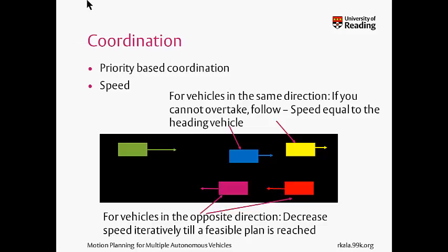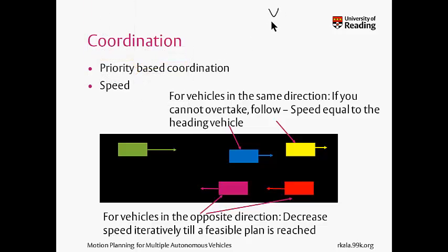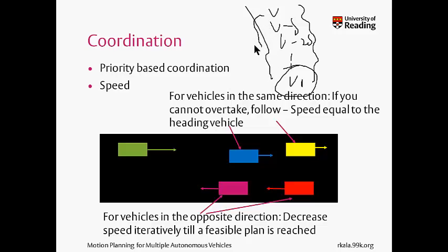The second thing that I said there was that speed is iteratively reduced from v to v minus delta to v minus 2 delta. Now this is a very bad procedure. I'm calling the complete RRT so many times in order to get the highest possible navigable speed here. I cannot waste this much time by calling the entire hefty RRT algorithm so many times. So here in RRT-Connect, what I say is that I call the RRT with connect at speed v, and I see what happens.